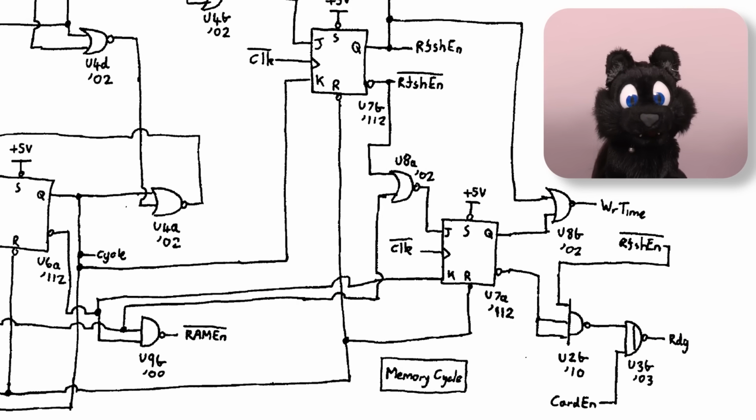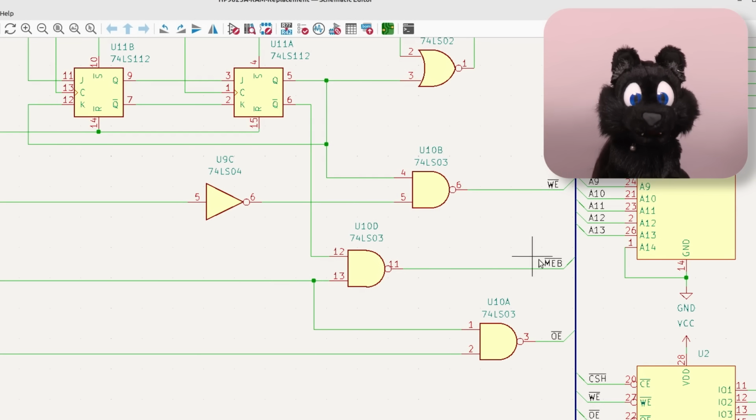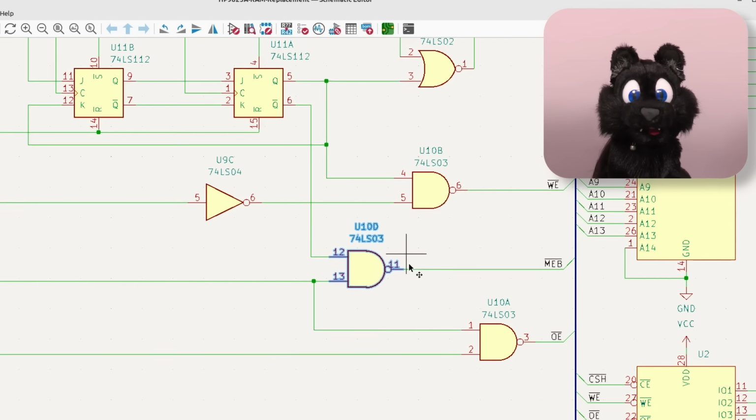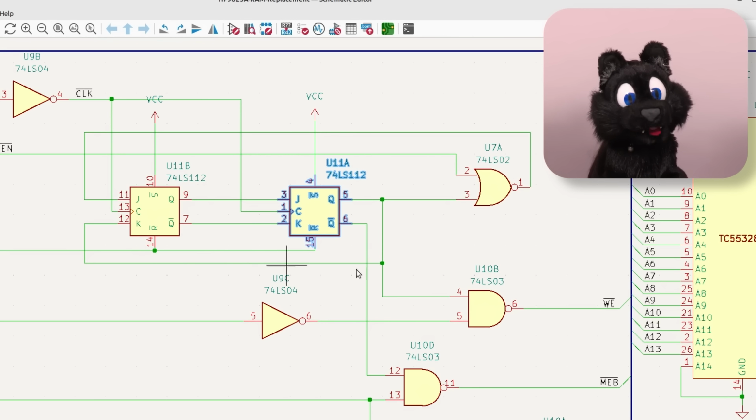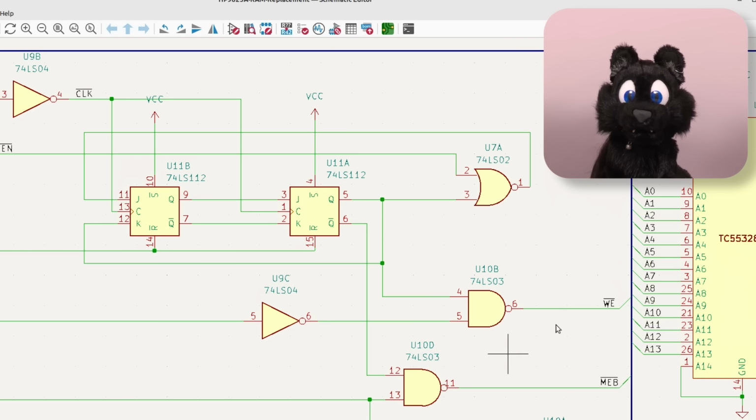The memory busy signal got driven from the refresh logic in the original. Since I'm removing that part, I'm simulating it with the delay line that is needed for the write access. This is the one part I'm not 100% sure about. Maybe it could be completely removed, but that is an experiment for later.